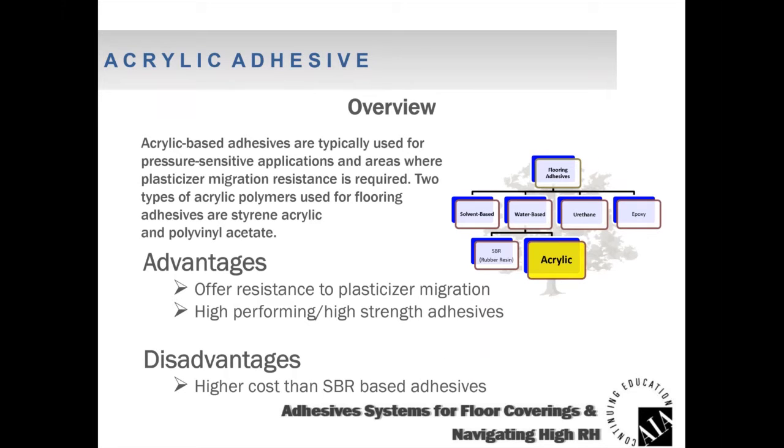Acrylic adhesives, made with water. Water's the carrier, acrylic's the binder, and they offer a very high resistance to plasticizer migration. They're a high-performing, high-strength type of adhesive. That's the new technology adhesive that you see on the market: acrylic materials. Disadvantage: typically more expensive than your SBR adhesives.